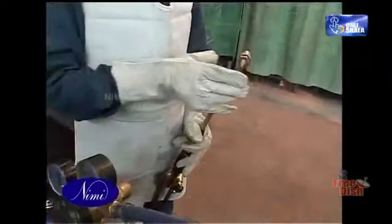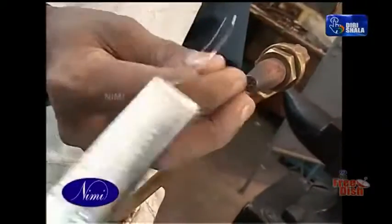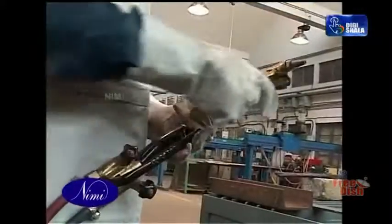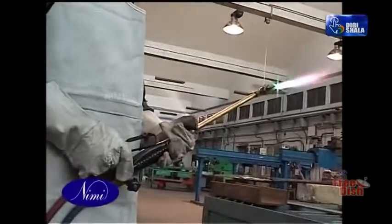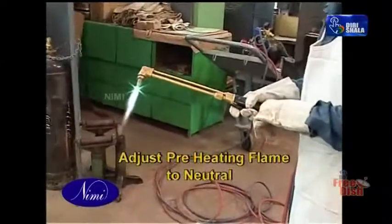In cutting operations, the stream of cutting oxygen sometimes blows the slag and molten metal into the tip orifices of the nozzle, which partially clogs them. This requires thorough cleaning. As the plate is of mild carbon steel, adjust the preheating flames to neutral.